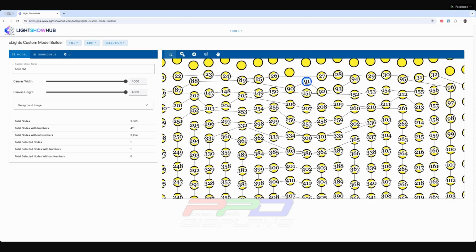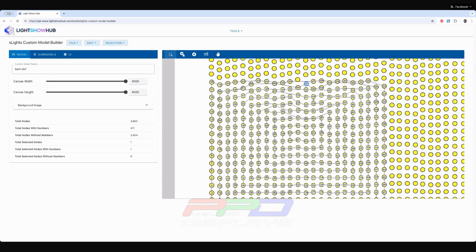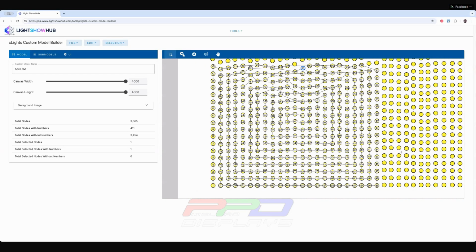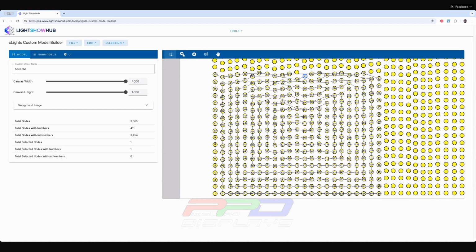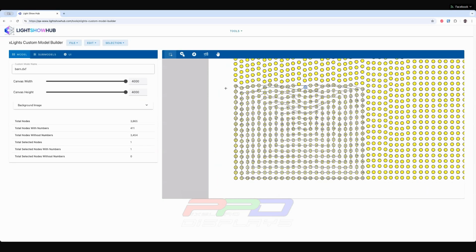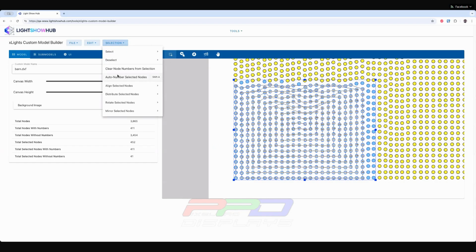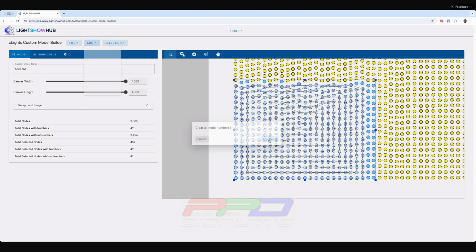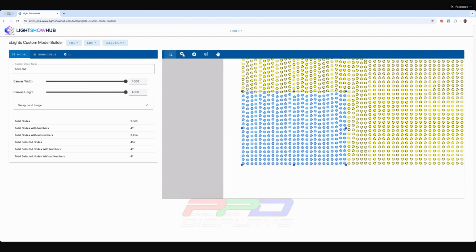It's looking in a radial direction to find the next value or the next point that is there with some fuzziness factor. The 91 was just outside of that range. But you can see here it did a pretty decent job still. It's still going in a circle and it's circling around into the middle. So for sections of your custom model, this really makes it super simple because you can do sections in a pattern and then connect them all together.